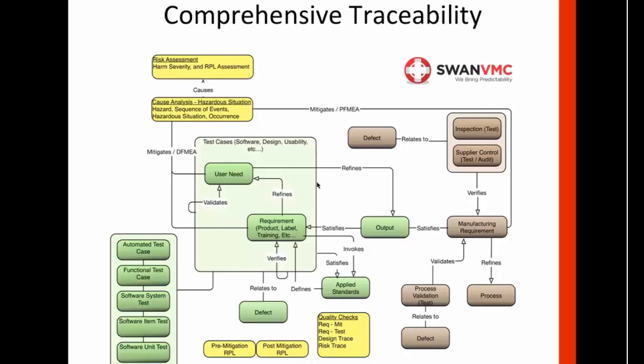of a verifiable process and a process validation, or you need a process validation to validate that requirement, or whether, say, a supplier is providing that service and you may need to assure that the supplier is properly testing that manufacturing process. So perhaps it's a supplier control or an audit of the supplier. And then, of course, we always have inspection that we can put in, either first articles or receiving inspection or in-process inspection, different kinds of performance-related testing to assure that the manufacturing requirement is verified.